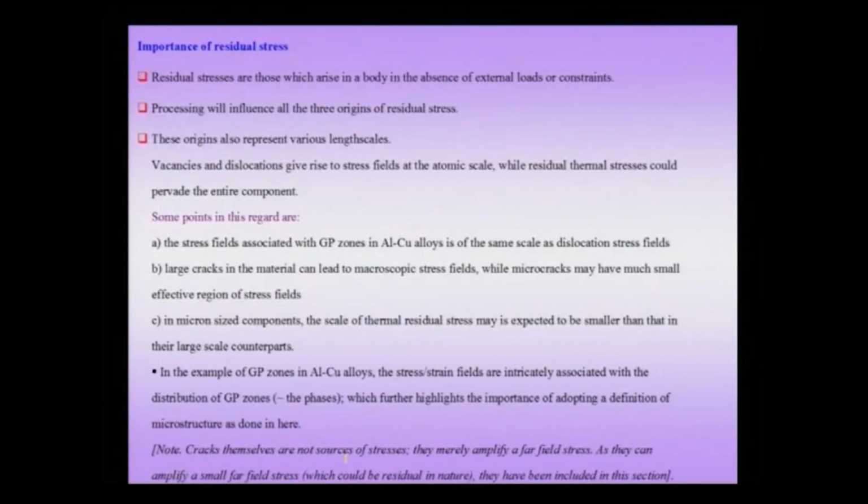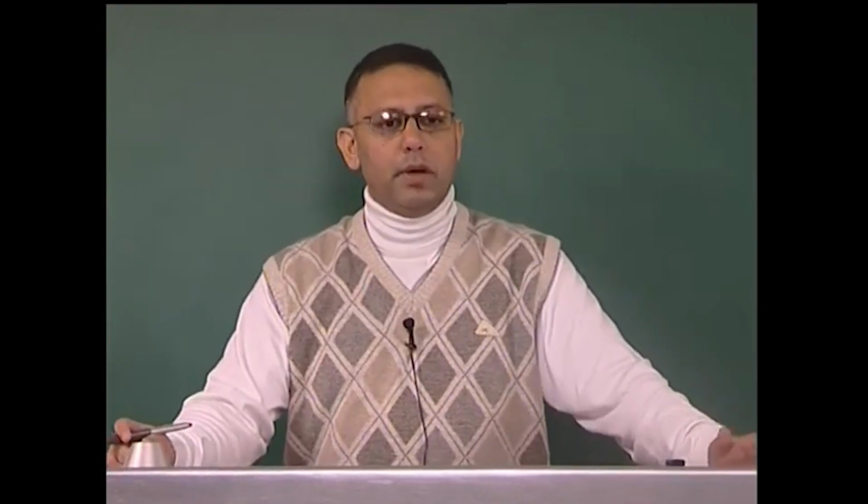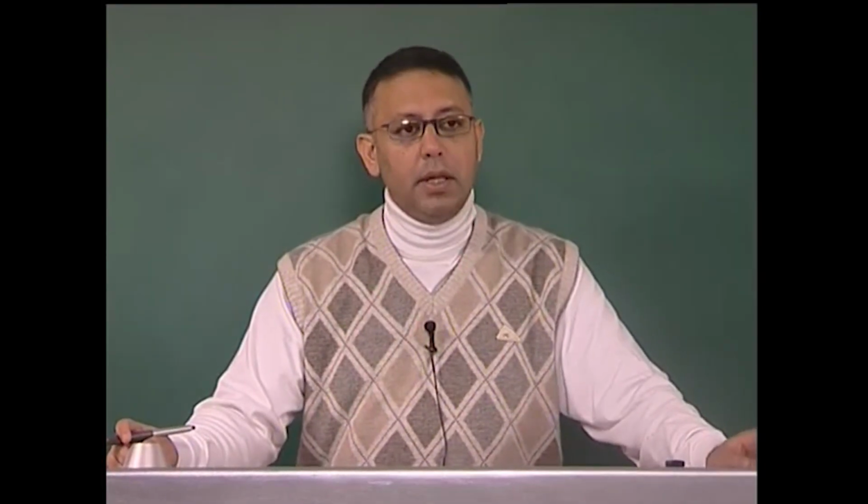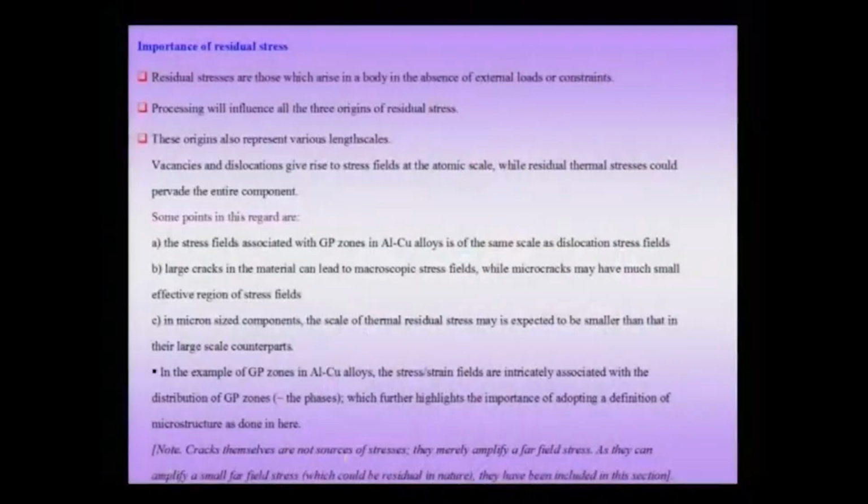Residual stresses are those which arise in a body in the absence of external loads or constraints. That is, if I put a load on a body or I give a displacement to a body, I do expect stresses to come about, but the stresses which remain after all the external constraints and loads have been removed are called residual stresses. Hence, residual stresses are those which arise in a body in the absence of external loads or constraints.